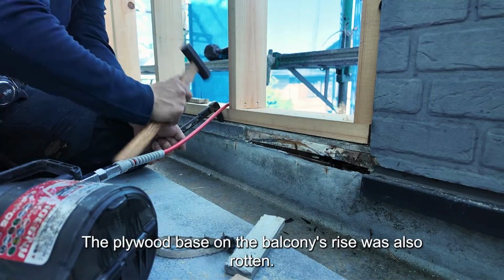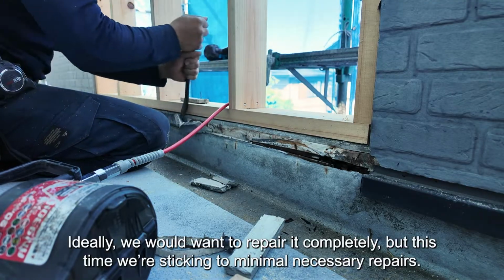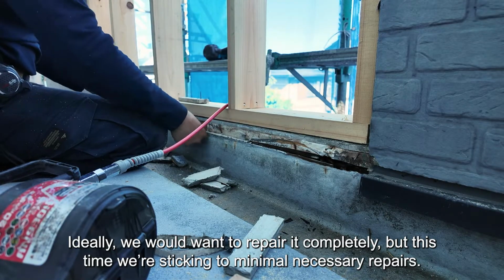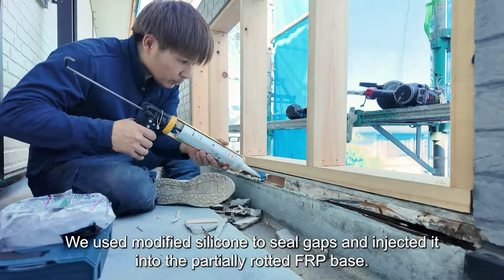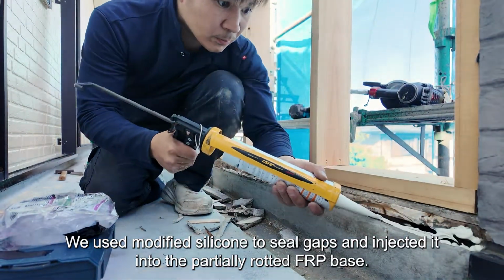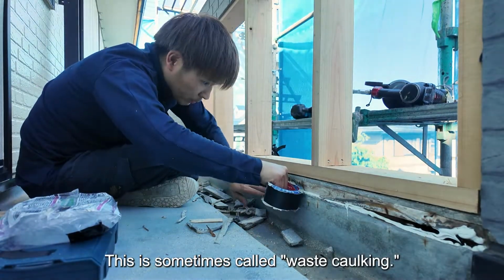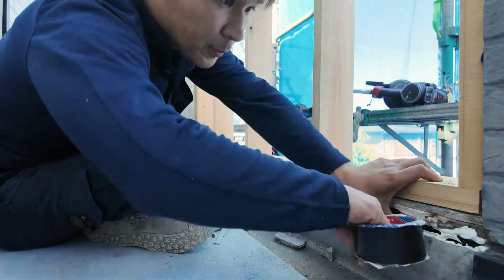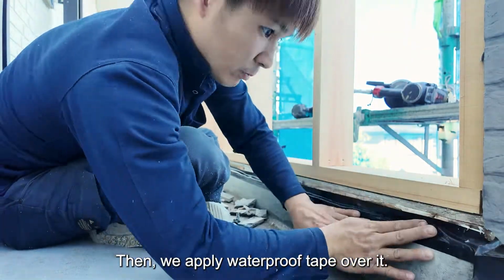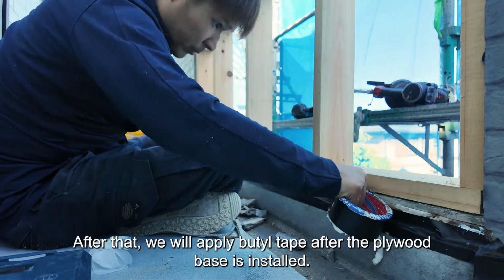The plywood base on the balcony's rise was also rotten. Ideally, we would want to repair it completely, but this time we're sticking to minimal necessary repairs. We used modified silicone to seal gaps and injected it into the partially rotted FRP base. This is sometimes called waste caulking. Then, we apply waterproof tape over it. After that, we will apply butyl tape after the plywood base is installed.